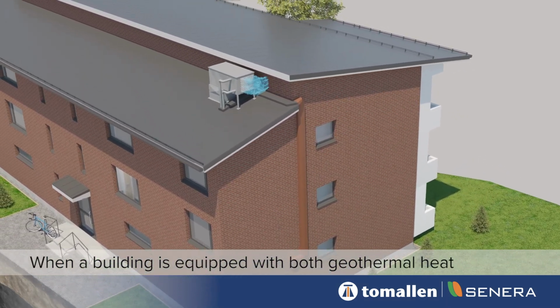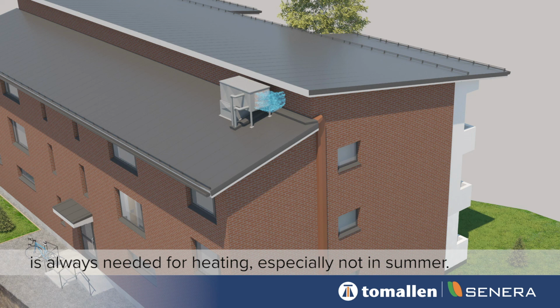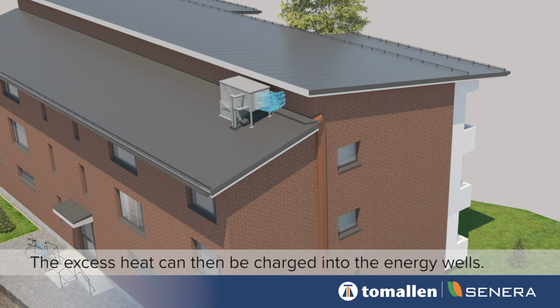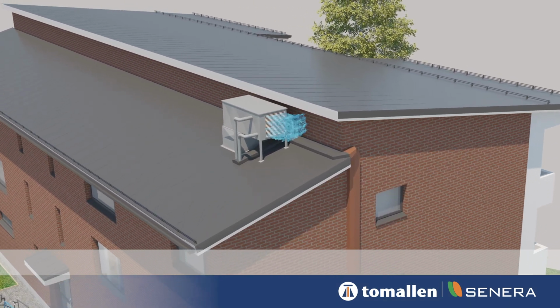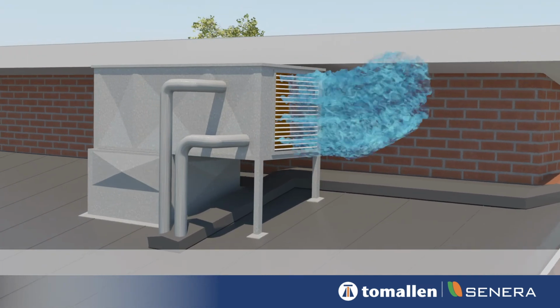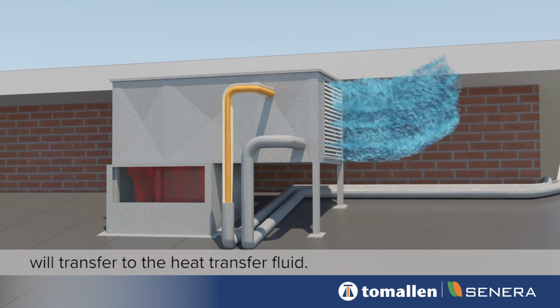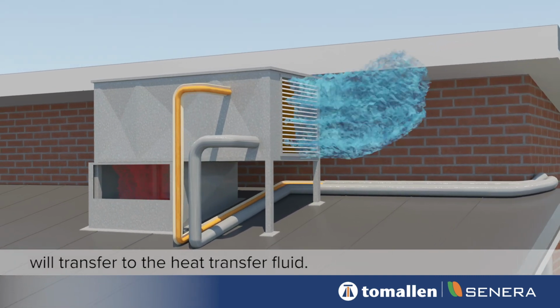When a building is equipped with both geothermal heat and exhaust air heat recovery, not all heat from exhaust air is always needed for heating, especially not in summer. The excess heat can then be charged into the energy wells. In the heat recovery unit, the heat of indoor air will transfer to the heat transfer fluid.